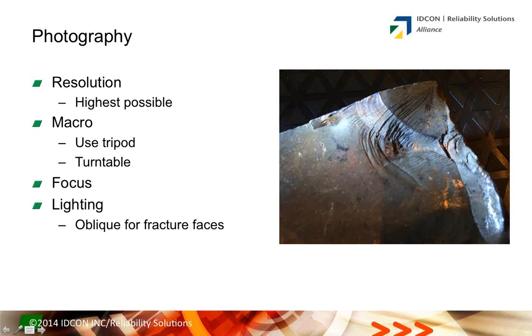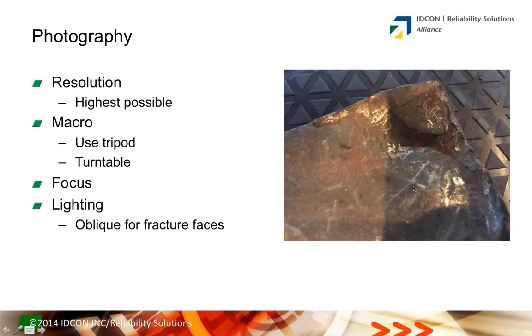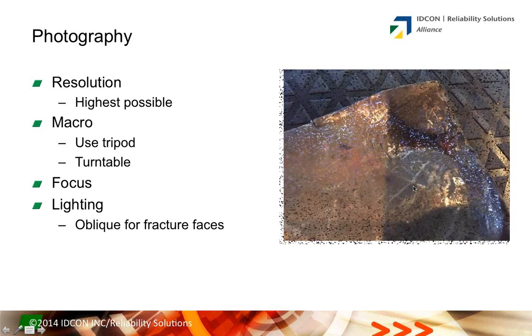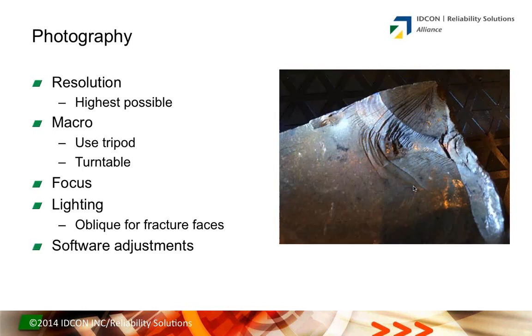And all I've done is get an LED flashlight, a little inexpensive LED, and illuminate it from the side, oblique lighting. And you can see immediately how these fatigue fractures show up and just pop off that face. If I go back, you can see the difference there pretty clearly. So good lighting and a camera is really great.